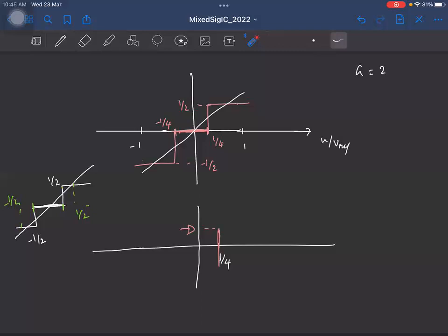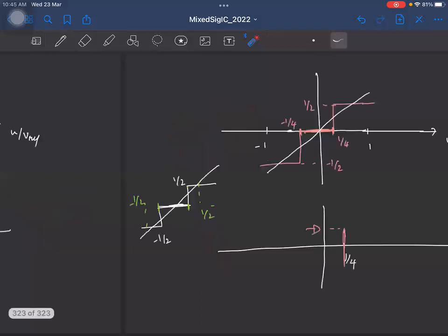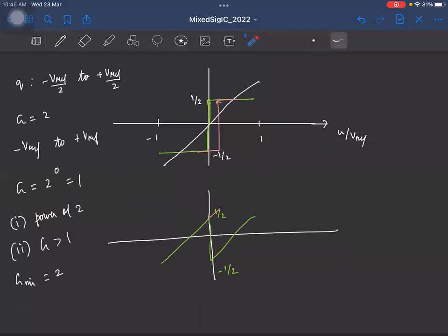Hold on. Let me correct you there. We are not introducing this to correct for offset. The offset might still be there. And as we saw, if you want to accommodate for this offset in these transition points, we have to choose a lower gain, right? But the moment we choose a lower gain, it turns out it's going to be 1, right? That's not going to help us. So the point is, if you just have 2 levels like this, you can't choose a lower gain to accommodate for the offset. So that is why we are introducing one additional level here.